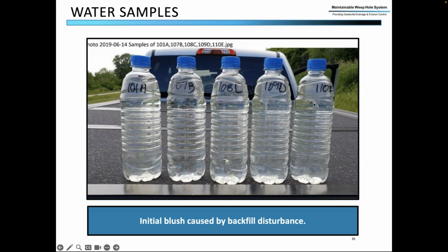One of the geotextile filter fabrics was a woven fabric, and the rest were non-woven fabrics. The woven fabric was not able to stand up to any type of cleaning, and this was known before we went into this test. It's just not strong enough. So our products come with non-woven geotextiles, which can fit all of the different soil types that you may be having in your situation.